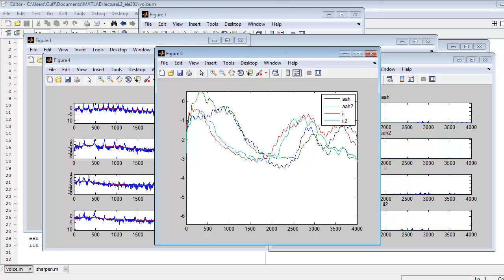Frequency shift? Something like that might work, but that wouldn't be linear time invariant. Let's just stick with a linear time invariant system, which means all it can really do is give me a frequency response. My E should come in, should hit my linear time invariant system, and out should come ah sound. So how do I design the impulse response?